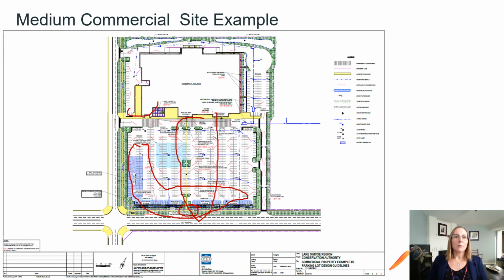The pedestrian walkways are raised to prevent additional snow or meltwater from accumulating. And then there are also heated walkways that are specified near the main entrances of the building. There are a limited number of vegetated islands to ensure clear paths for snow clearing equipment. And then in other areas, they use those painted end markers that I discussed. And the drawings also specify the use of deciduous trees for those features. And again, as you can see here, which we've mentioned in the drainage area, sorry, it's getting pretty marked up here, you can see that there are relatively small areas, graded at 2 to 4%, draining to each catch basin.